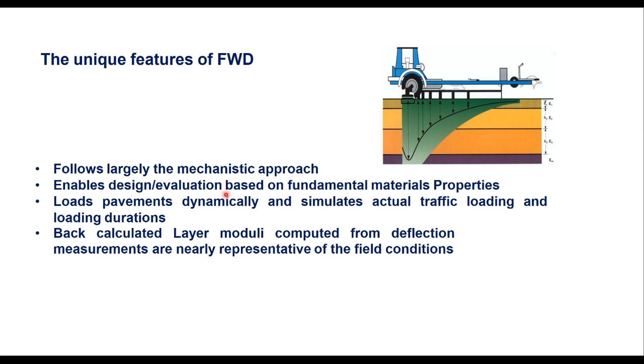It enables the design or evaluation based on fundamental material properties. Load on the pavement dynamically simulates the actual traffic loading and loading duration. The back-calculated layer moduli computed from deflection measurements are nearly representative of the field conditions. So these are unique features which are not available in Benkelman beam deflection study.